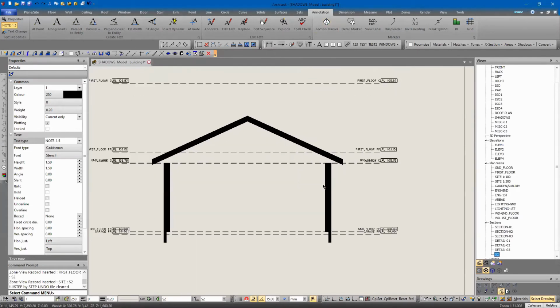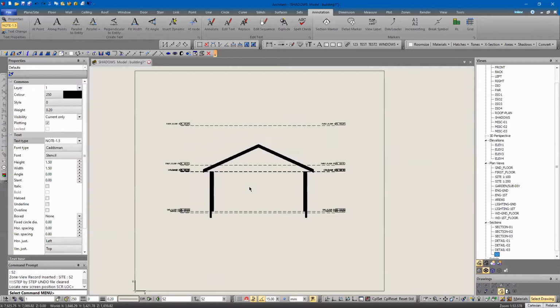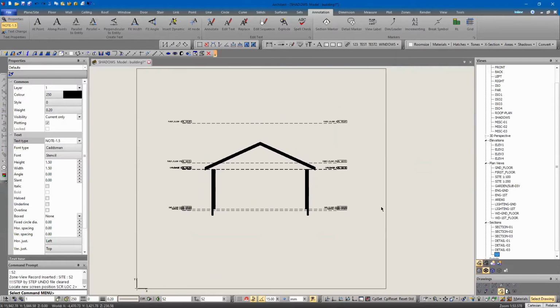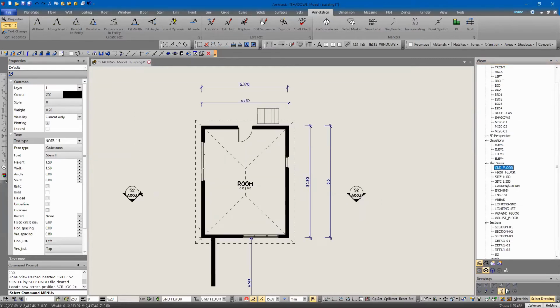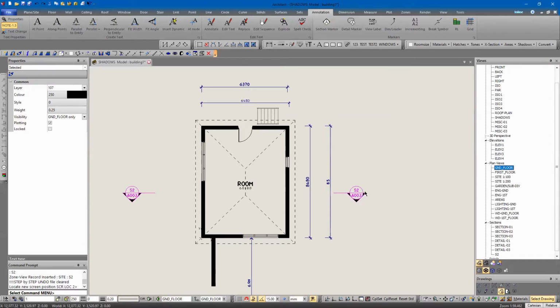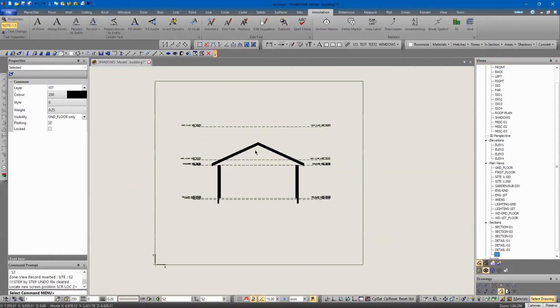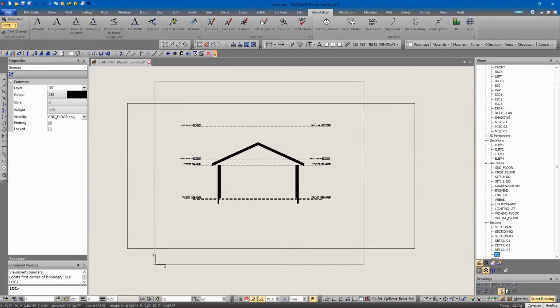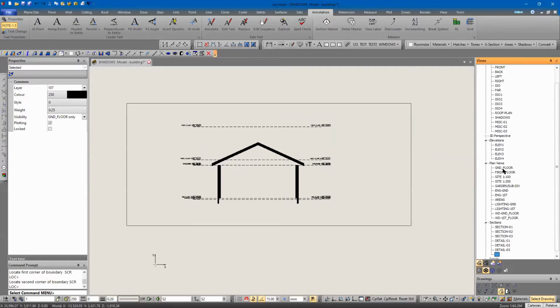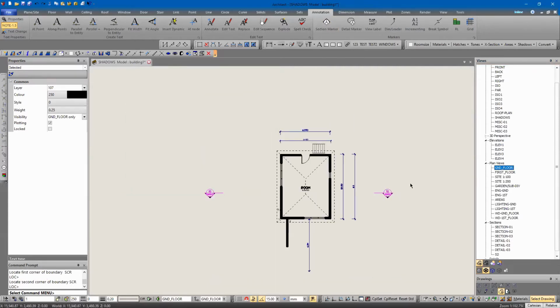That'll zap through, creates our new section, and the extents of the plot boundary that's created is the extents based off here to here. I think it's the outer edge of those two markers. So if in your section you decide you want some extra space around it for extra notes and do something like this to it, when you go back to your plan, you'll find that it's actually moved the markers. So that's one of the disadvantages in using this tool.